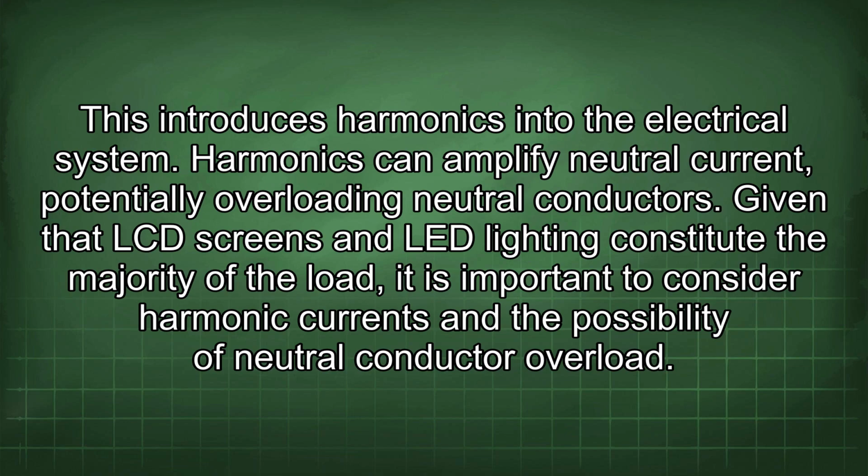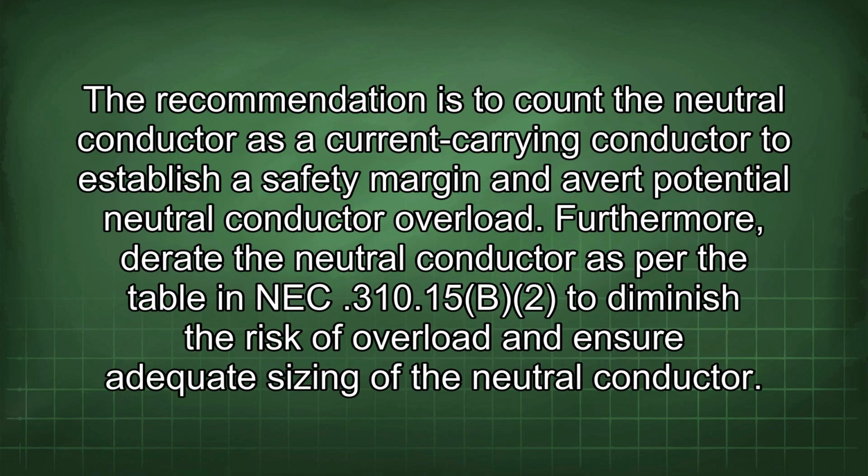Given that LCD screens and LED lighting constitute the majority of the load, it is important to consider harmonic currents and the possibility of neutral conductor overload. The recommendation is to count the neutral conductor as a current-carrying conductor to establish a safety margin and avert potential neutral conductor overload. Furthermore, derate the neutral conductor as per the table in NEC 310.15(B)(2) to diminish the risk of overload and ensure adequate sizing of the neutral conductor.